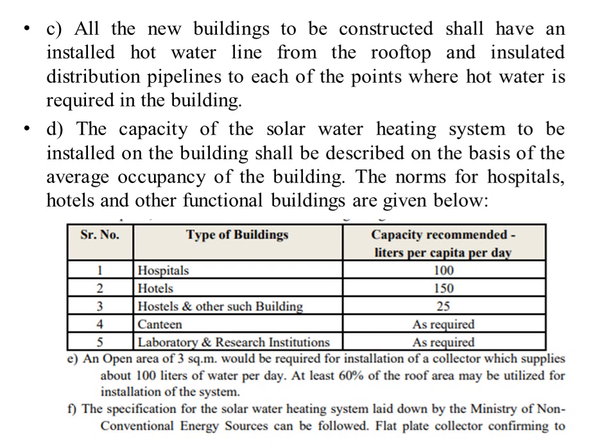For example, for hospital, 100 liters per capita per day is the requirement of hot water. Similarly, for hotels, 150 liters per capita per day. For hostels and other buildings, 25 liters per capita per day, canteen as required, laboratory research institution as required.